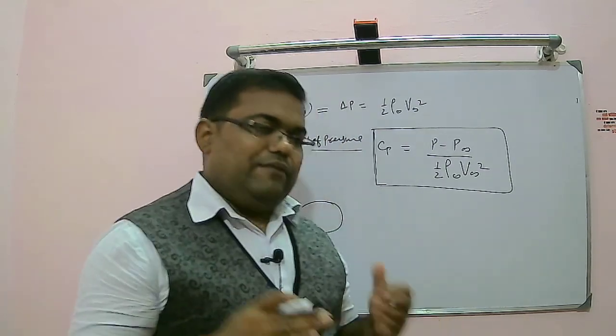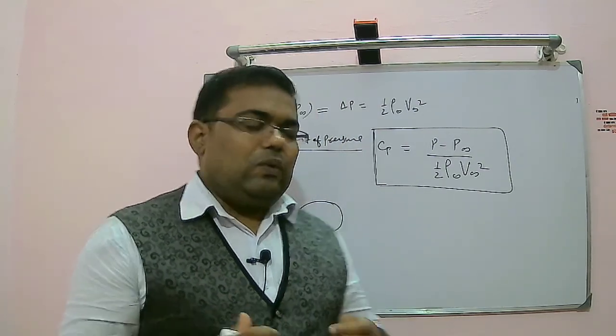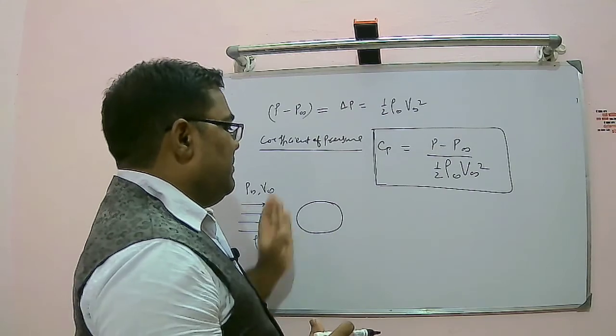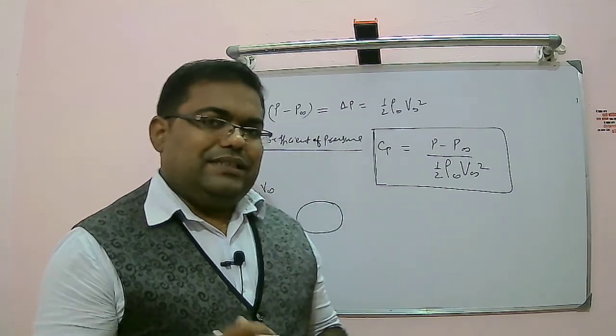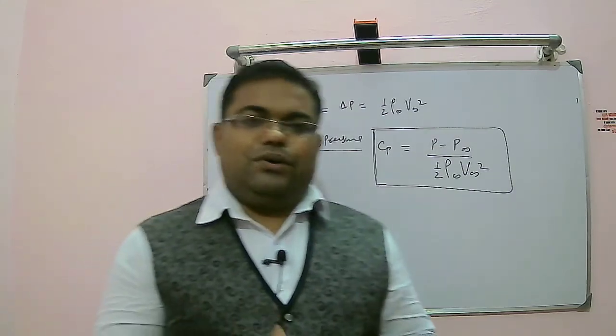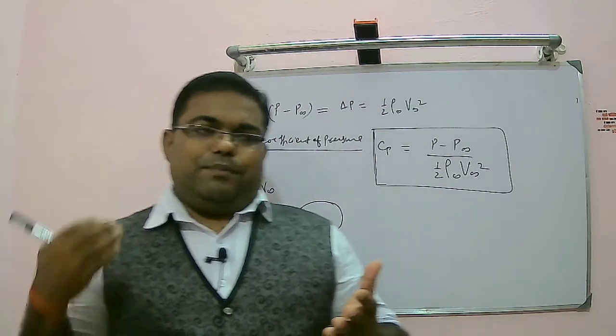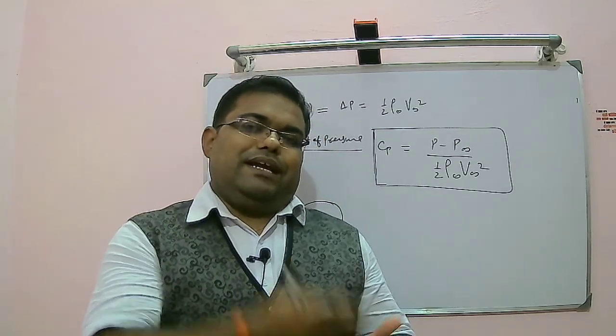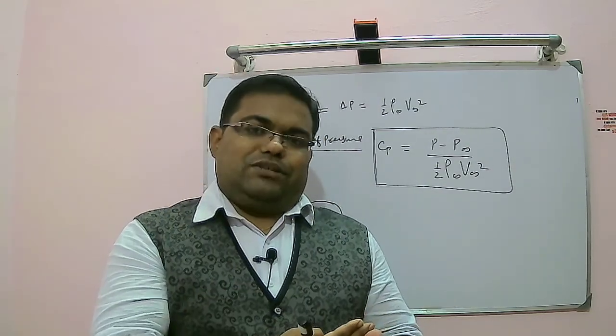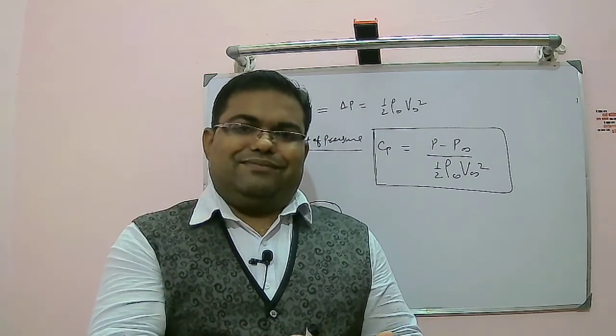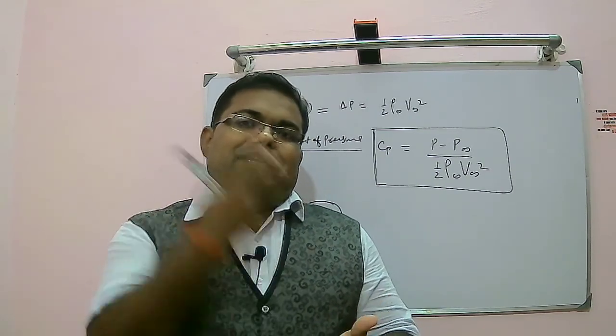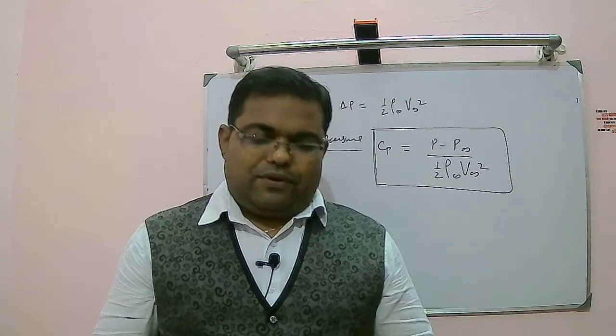So now I want to basically know how actually pressure is behaving over this object. First thing, from the boundary layer concept, whenever flow is coming, the point where it is going to strike the object will be called a stagnation point, or you can say the no-slip condition will exist at that point, and immediately after that boundary layer formation takes place.